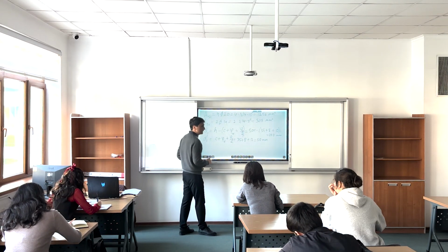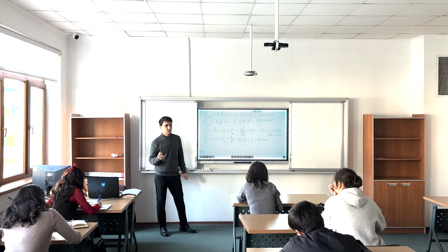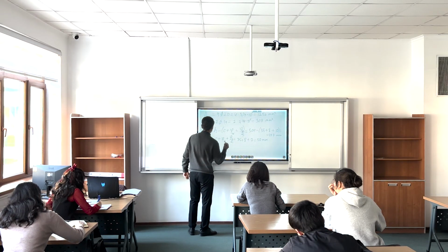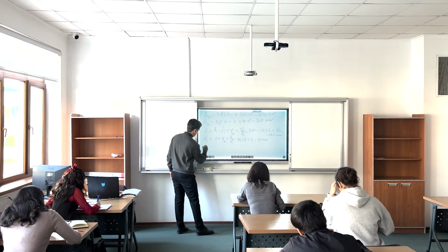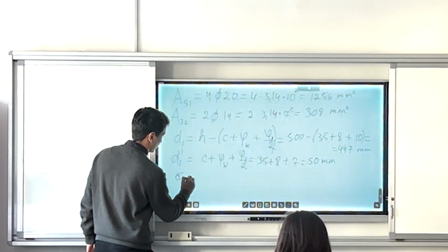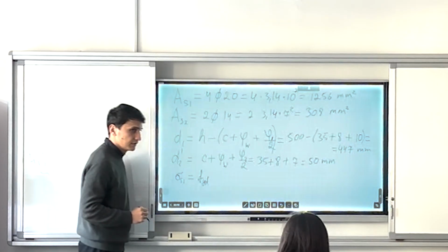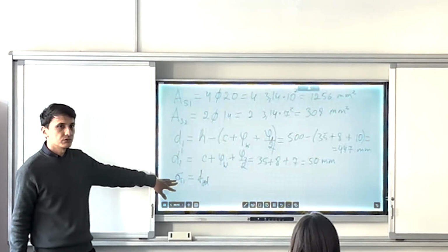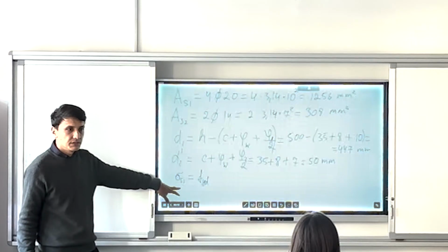So yielding is happening in the bottom rebar because we have positive yielding bending moment we're trying to find. Okay? So it means if it's in the bottom reinforcement, sigma at the bottom reinforcement will be equal to the FYD. So this is the critical point where we should start. It means the yielding, the bottom reinforcement is being yielded.